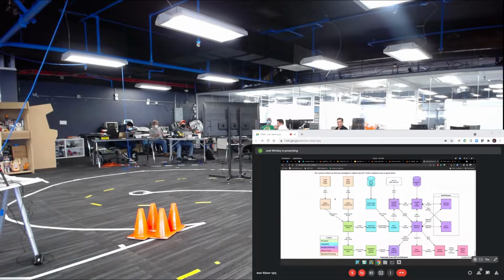You take input from two LiDARs, front and rear. You transform each of those because when you're talking about sensor data, it comes in the frame of reference of that sensor, right? So you have to move that to a common frame that's common to the whole vehicle so that you can fuse it together. So for each of the LiDARs, we transform all the points and move them into the frame of reference of the car, and then we fuse it together with point cloud fusion.